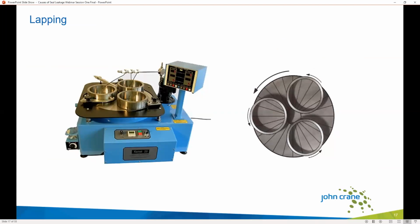The way that we manufacture them to be so flat is through a process known as lapping. What we're seeing here is a standard lapping machine. The way that it works is we would get the component which needs to be lapped, and we would put it on top of this plate here on the top of the machine with some kind of abrasive compound. As the lapping plate spins, that slowly, using the abrasive compound, wears away the face until it is flat.